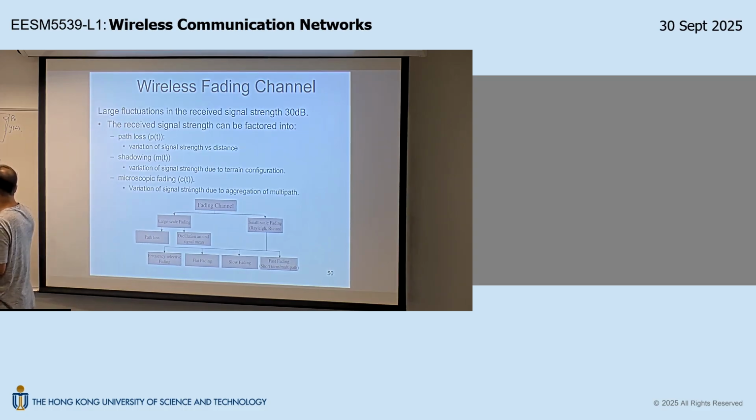It's just a more complicated parameter to define the behavior of this black box. All this physics, all this multipath propagation will be completely encapsulated into this two-dimensional impulse response. Once you know about this, you can forget about the physics and just treat the connection between the transmitter and receiver as this black box and forget about the physics involved. Is that okay? So that's the beauty of so-called channel modeling.